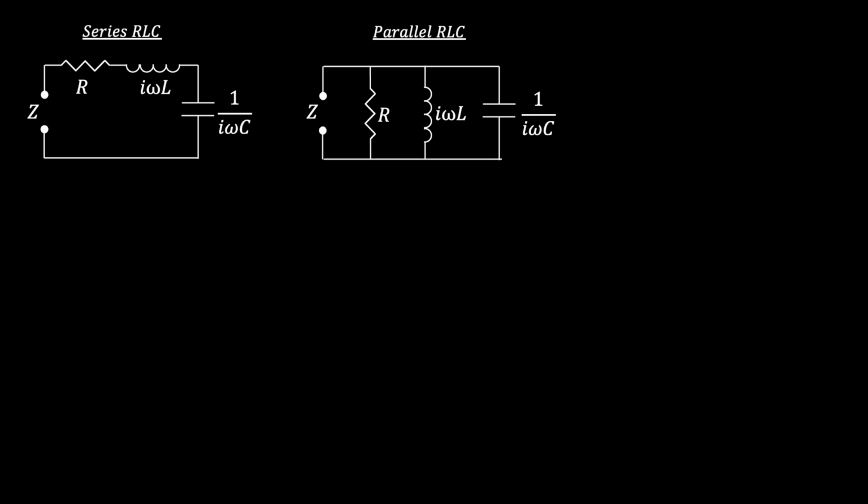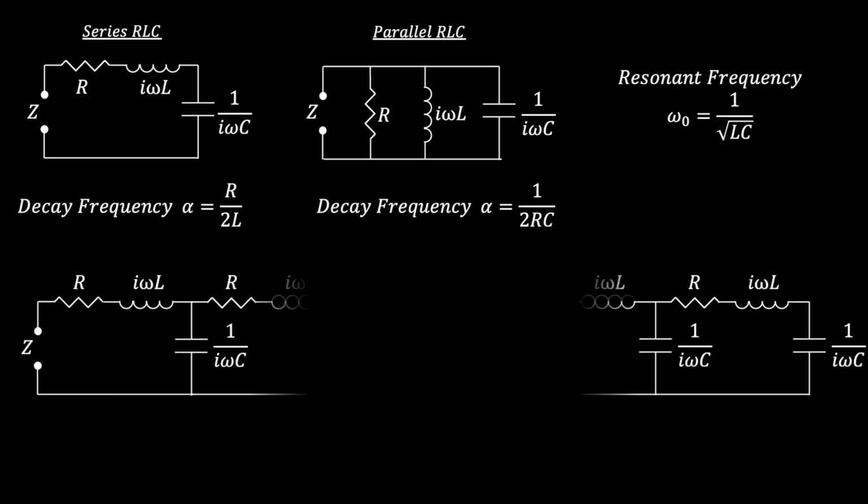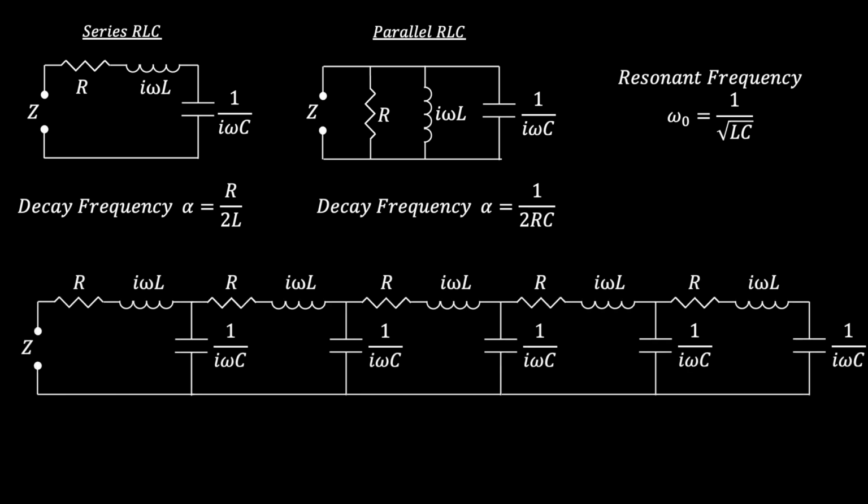In electronics, the common explanation of resonance uses either a series or a parallel RLC circuit. These basic examples are good for explaining the basic concepts, such as resonant frequency, but the derivation of these concepts becomes much more complicated when multiple circuit elements are included, which is a useful thing to understand if your circuit of interest is, for example, a power line that uses many capacitors to boost voltage along the circuit. What would the resonant frequency or frequencies of this circuit be?